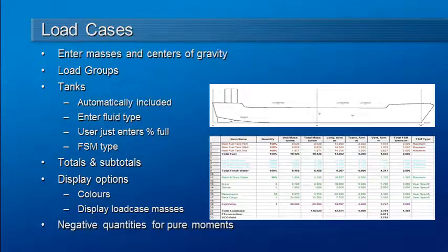Before we can carry out equilibrium or large angle stability analysis, we need to have a series of load cases defined. Hydromax has an integrated load case editor, and that allows us to enter a list of masses and their respective centres of gravity. It's also possible to group together commonly used sets of masses into load groups. So one common example would be the lightship condition with all of the standard loads that are permanently fixed to